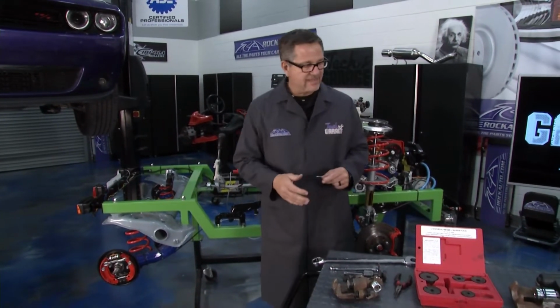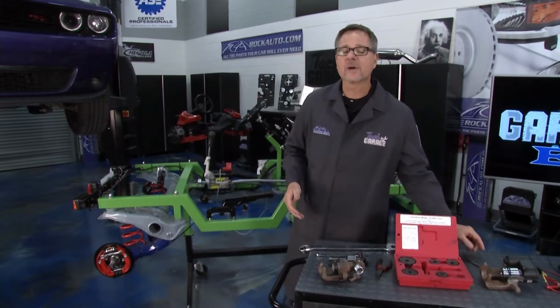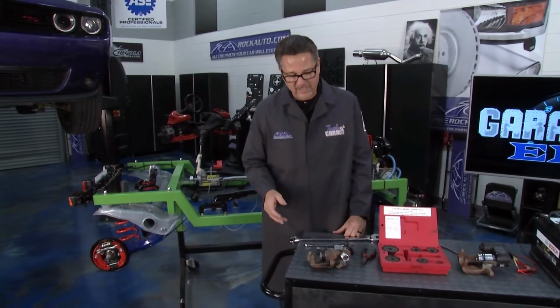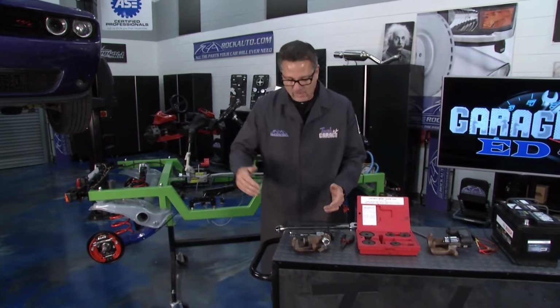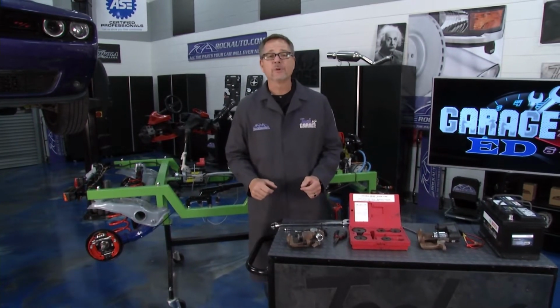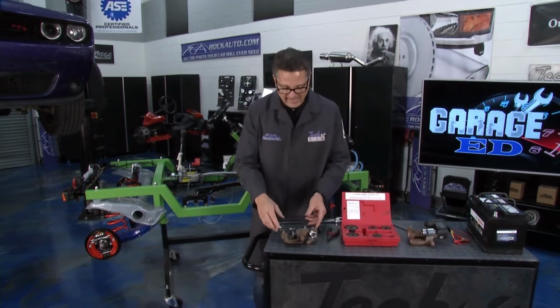Now you may have one that's a caliper. Calipers also have emergency brakes built into them. Throw up the red flag. Stop. We're so used to pulling these in. When we put a C-clamp on them, we push it in. We can destroy this one. How are you going to know?